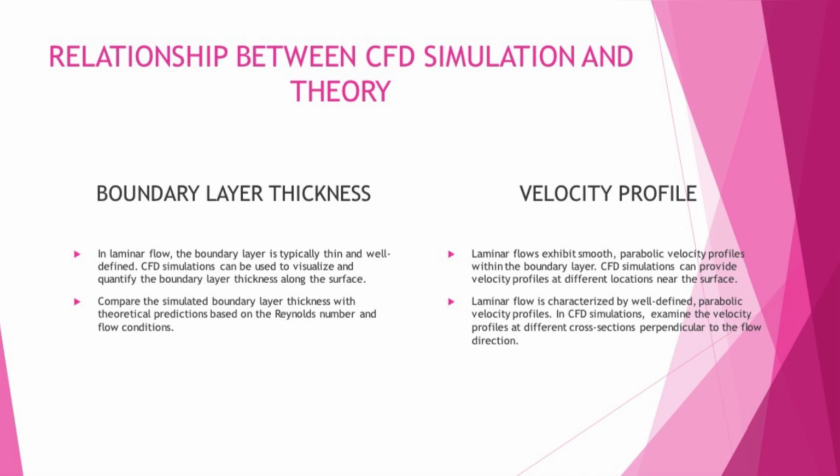Next, we go to the relationship between CFD simulation and theory. At the side of the boundary layer thickness, in laminar flow, the boundary layer is typically thin and well defined. CFD simulation can be used to visualize and quantify the boundary layer thickness along the surface. Compare the simulated boundary layer thickness with the theoretical prediction based on the Reynolds number and flow condition.